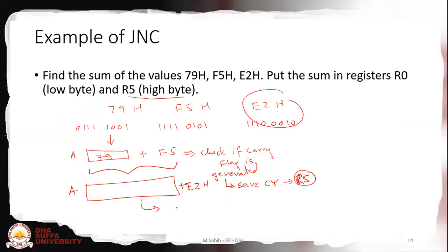And then again, we will check if the carry flag is 1. If yes, then we will increment R5, or add this carry flag to the R5 register. So this is how it is going to work.